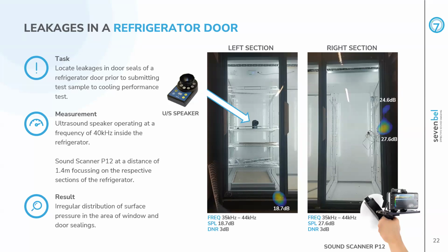And if there were leaks over time, humid air would be sucked into the refrigerator, would essentially be deposited on the fan blades, and would eventually cause reliability issues further down the road. So this is why it's critical to prove not only during the product design and product verification phase or testing phase that a product is airtight, but also, of course, when it's final tested, end of line, and when it's also brought to the field and to the end customer.